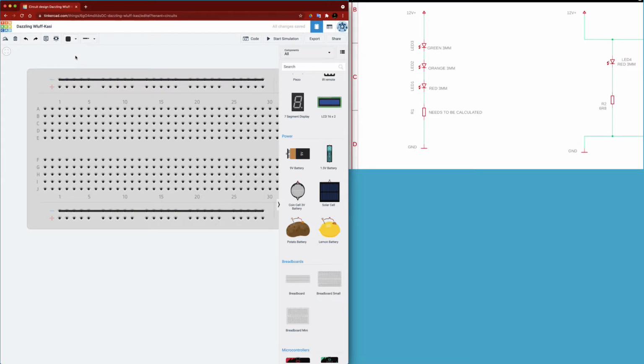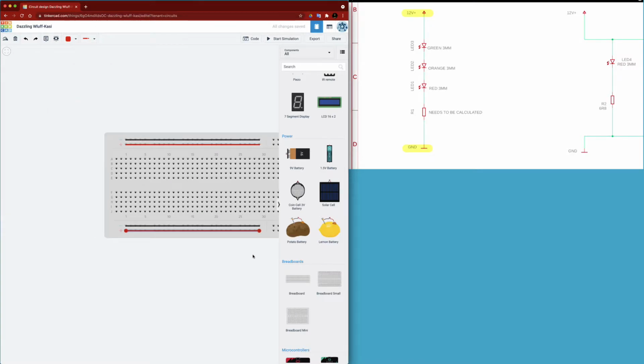Now on the schematic drawing, if we look over to the left, that is going to be the ground right down there, which is symbolized by that upside down T. Okay, well, what about the one at the top, which is the arrow that's pointing upwards, and it says positive 12 volts beside it? Well, that is the positive rail, and positive is represented by the color red, and it would be these 25 holes right here and these 25 holes right there.